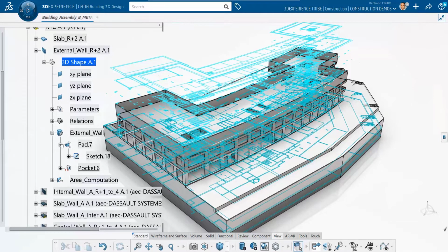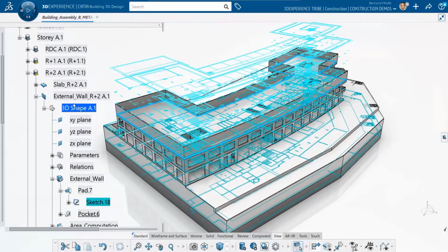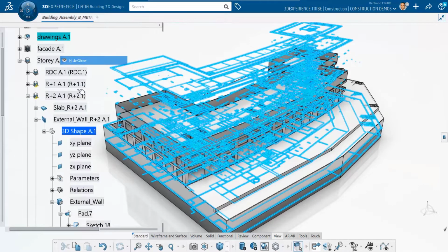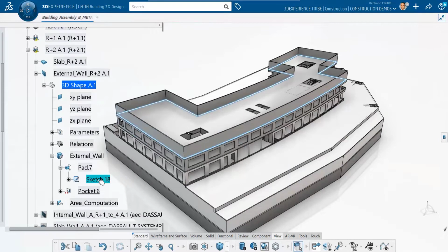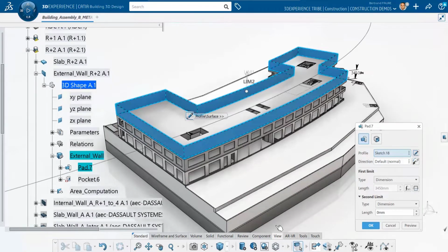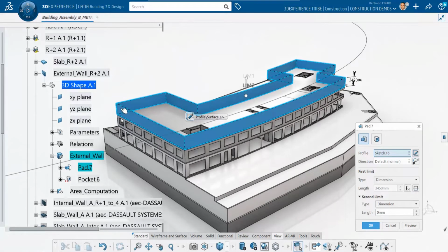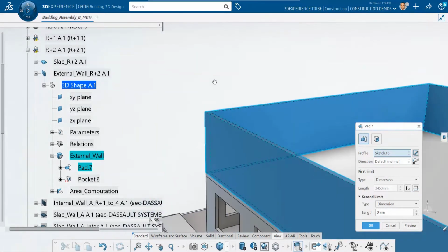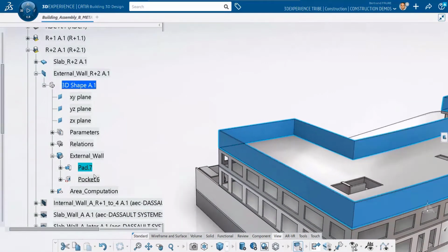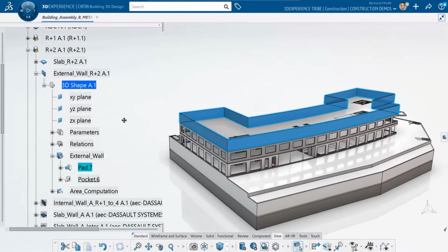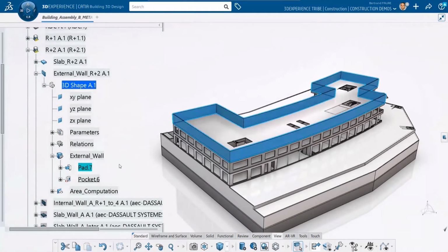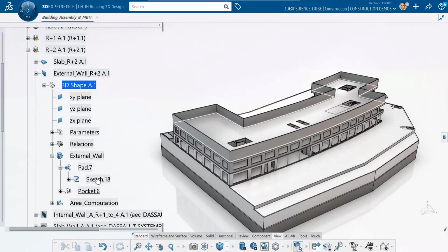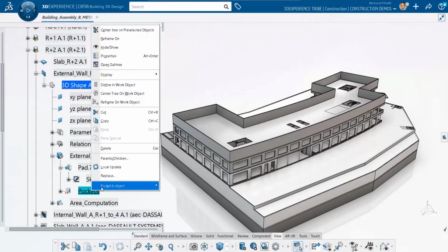The second reason why I'm so happy that Raymond cleaned up the drawing for me in DraftSight is because I'm going to use a profile to extrude the wall, for example, like I'm doing here. And the 3D geometry will inherit the quality of the profile. So the idea is to control the quality of the generated 3D. That's why it's important that the drawing is not directly the drawing given by the 2D designer, but really cleaned for the purpose of being reused in 3D.